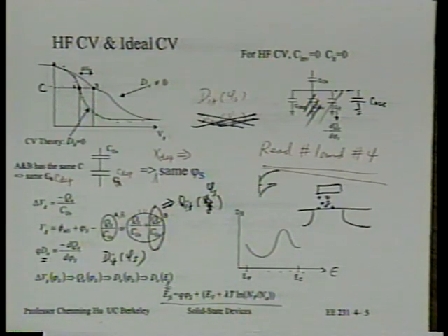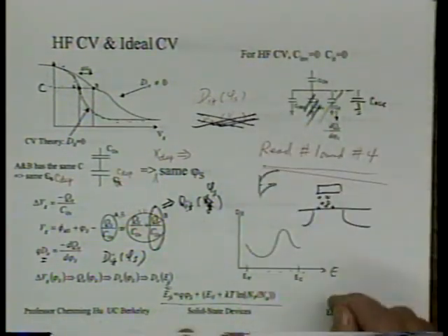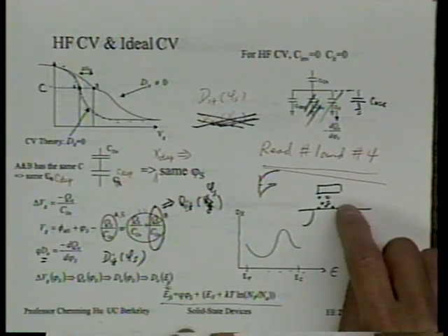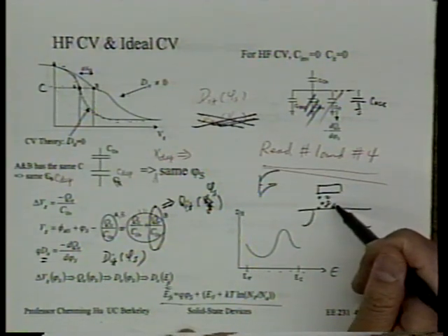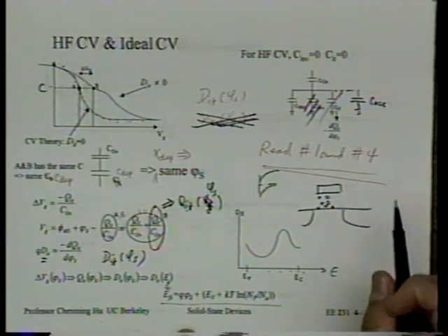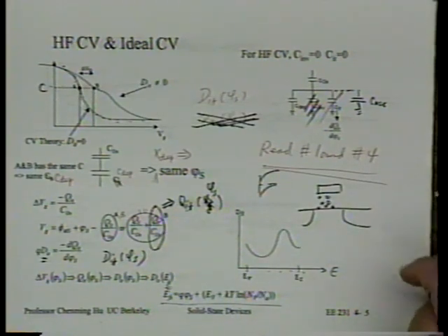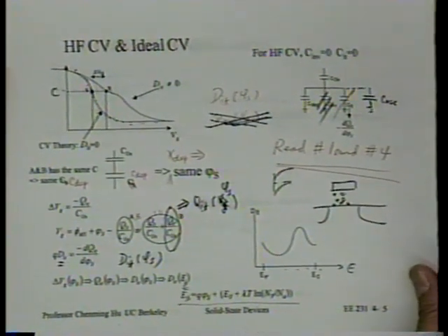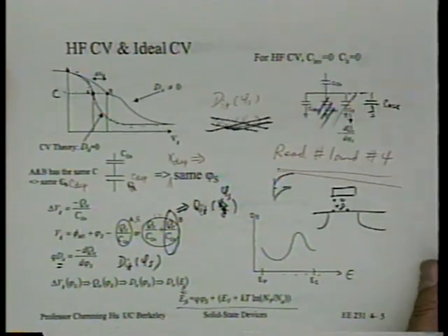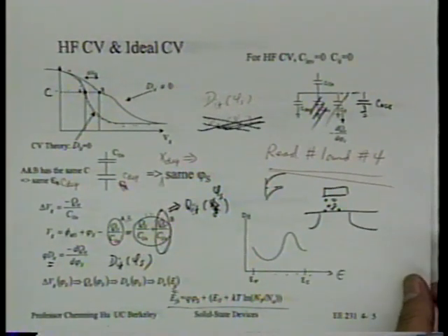This 1/f characteristic comes from the assumption that there's a continuous distribution of traps in this spatial distribution. And furthermore, we assume the time constant is an exponential function of the separation between the trap and the silicon. When you make those two approximations, you end up with 1/f noise. If you haven't heard this term, I'll introduce it later, but some of the circuit design students probably have heard about it, and that's related to this. So the assumption is it's all semi-continuous.